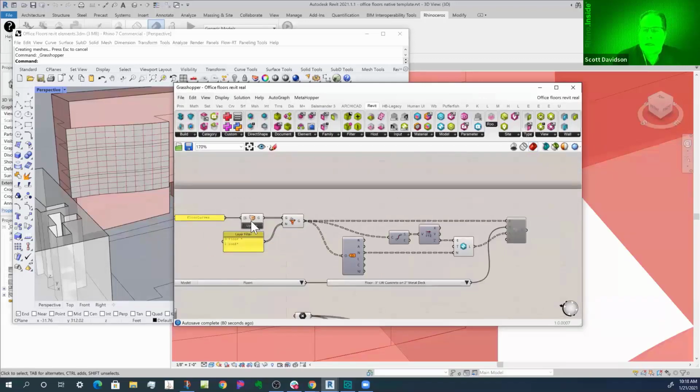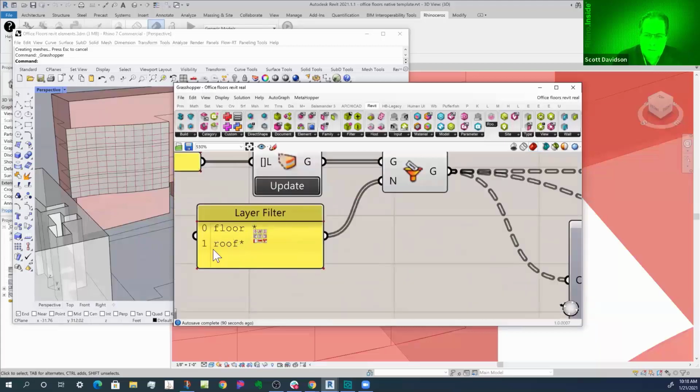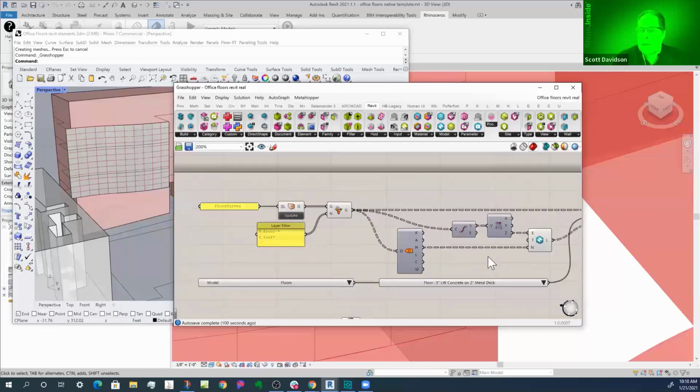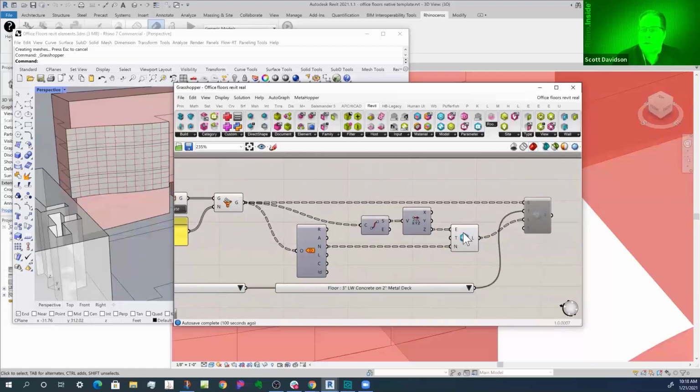So in this case, I'm going to take some floor curves, and I'm going to find all the curves on floor and all the curves on roof. And then I'm actually going to find the name on those curves, and I'm going to find the elevation of the curves, and I'm going to create a new Revit level.